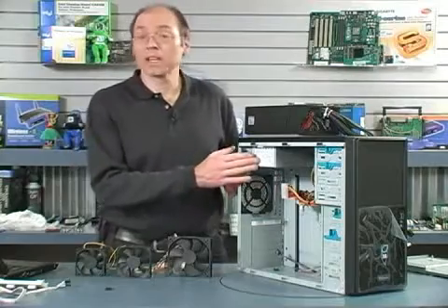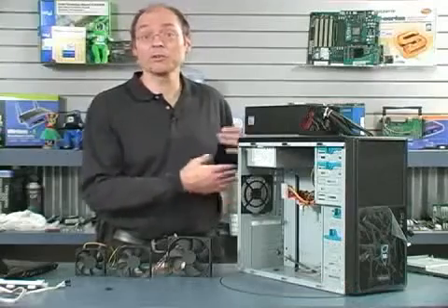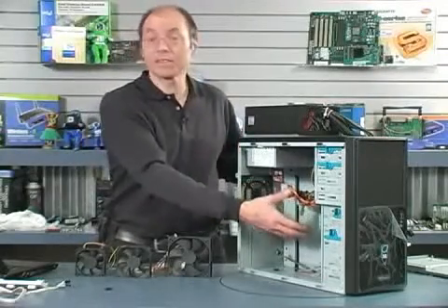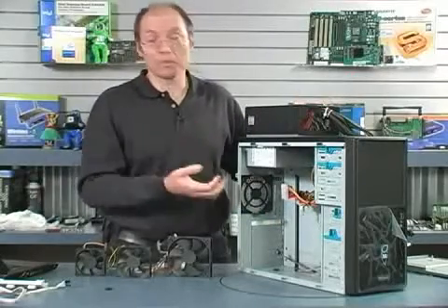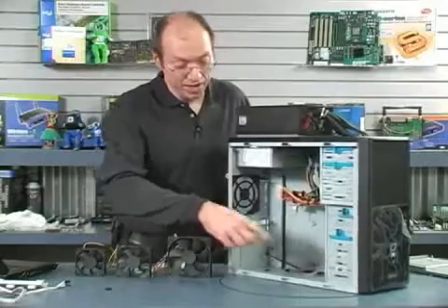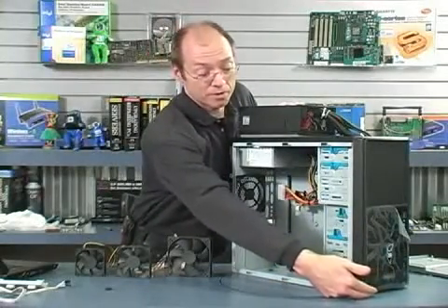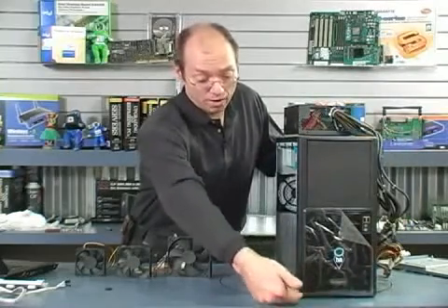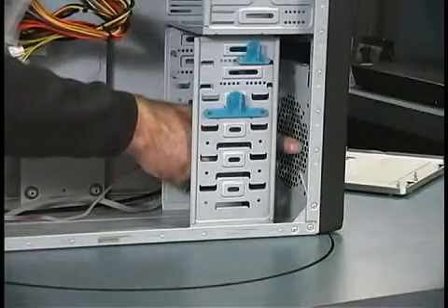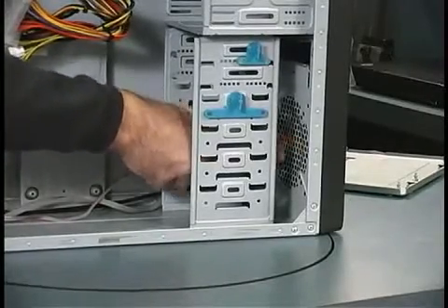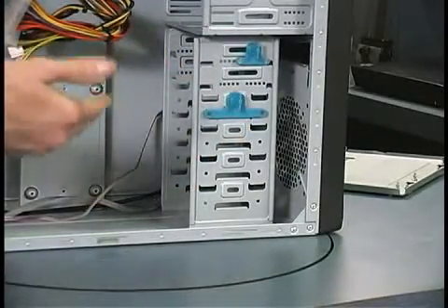Now, power supplies also have fans, and the power supply will also exhaust air out the back. So now we've essentially got two fans pulling air from inside the system and exhausting it out the back. Now, where does that air come from? It has to get into the system somewhere. Well, almost all chassis have a vent on the front, and usually it's down below. There's an opening in the front panel, down at the bottom here, where air will go in, and if I turn this case around, you can actually see where it will flow in through the front of the case here. Many chassis like this one not only have openings there, but there's actually a mount for a secondary fan.